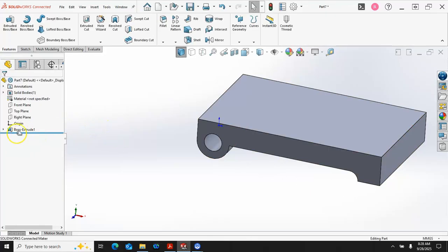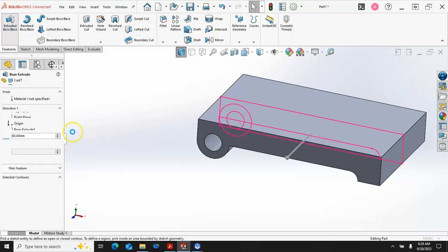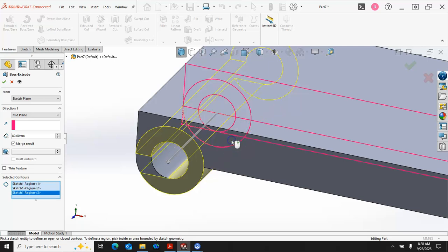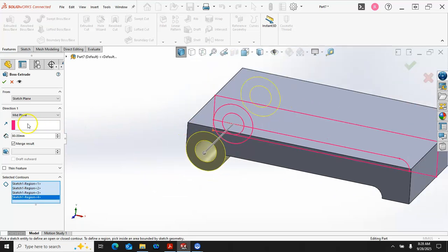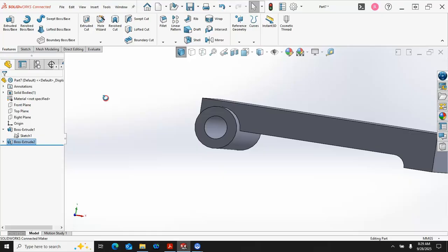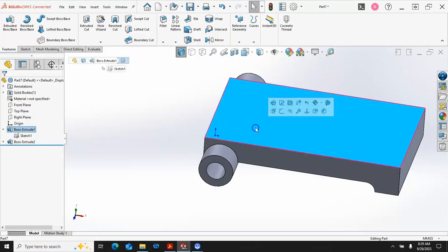Now, I have a couple of choices to finish the boss offset. So this circle piece that extends past, we're going to extrude, go back into, and pick just the geometry for those guys. Stays in midplane, then I can go 110 as the outside. All right, so that goes all the way through. I do want to make sure that it goes all the way through because I have closed those off before. However unintentional it was, it does happen.